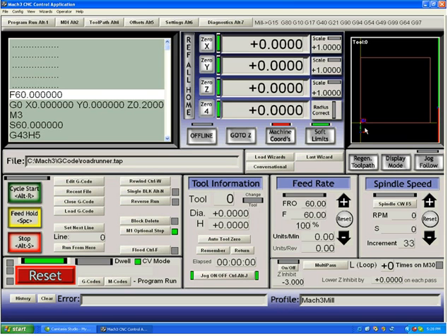These are the things that the machine coordinate system takes care of. They're very important that they never get changed, so there is only one way to change machine 0, and that is by homing. Referencing your system to the home switch is the only thing which will change the machine coordinates. So let's take a look at our secondary system by turning this off. We're still on a toolpath display showing my entire mill. If we were to jog, you can now see me jogging across my mill table.